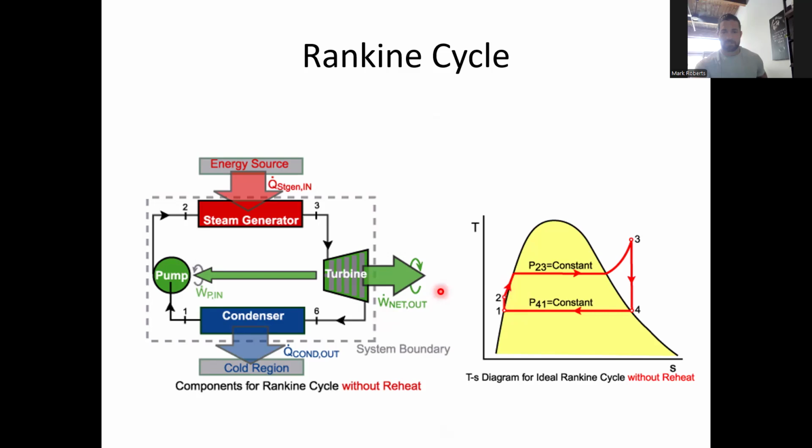The next part of the process: we have this subcooled liquid, and now we add heat. So we need to follow a constant pressure line. The subcooled liquid is first going to increase in temperature as it gets heated until it gets to the saturated liquid, and then it's going to stay at constant pressure, constant temperature as we go through this vapor liquid equilibrium. And then once it's all saturated vapor and we continue to apply heating to it, that's when we